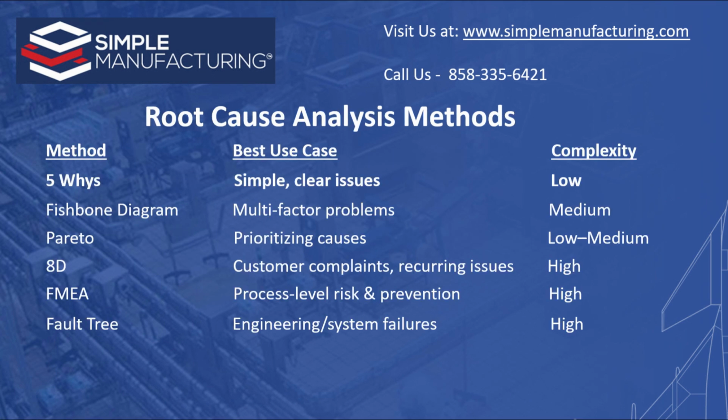There are several methods for determining root cause. Those methods are 5 whys, fishbone diagram, Pareto, 8D, FMEA, and fault tree. The use of and complexities vary between each. Simple Manufacturing has the 5 whys method incorporated in its process. It is the simplest of them all and not complicated to use, and when used, it usually results in determining the underlying cause or causes. The 5 whys method is simple, asking why multiple times, typically 5, until the underlying issue is found.